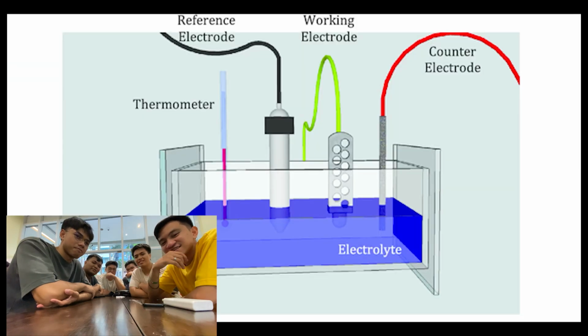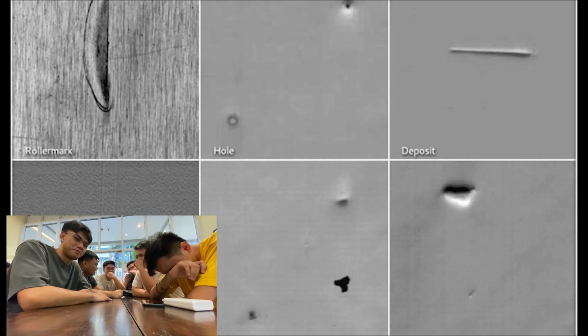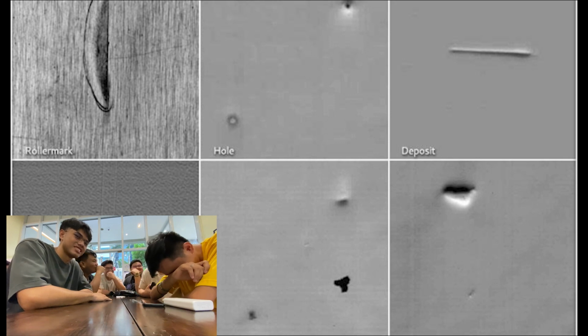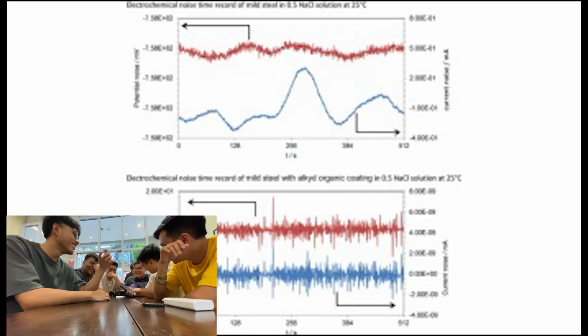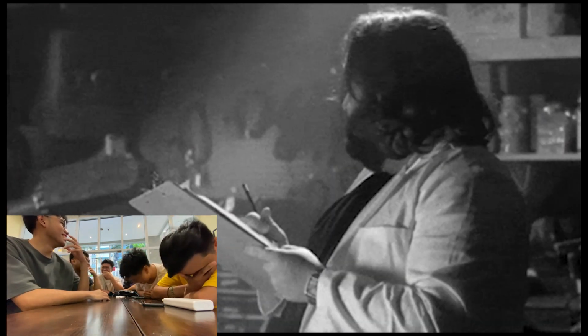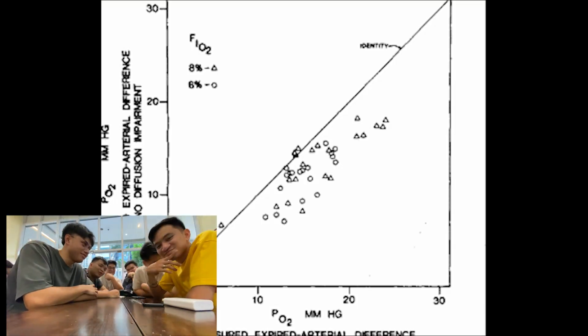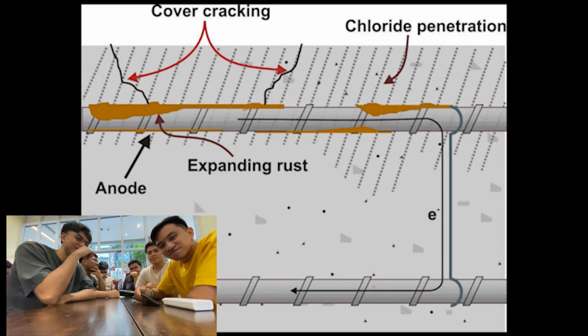Detection: detecting concentration cell corrosion involves a combination of visual inspection, electrochemical testing, and monitoring of environmental factors. For visual inspection, they look for areas of surface irregularities, including small pits or cracks, which may signify the presence of anodic and cathodic sites. Electrochemical testing techniques such as electrochemical noise analysis or polarization resistance measurements can provide quantitative data on corrosion rates and reveal the presence of concentration cells. And monitoring environmental factors such as oxygen concentration and temperature can aid in detecting conditions conducive to concentration cell corrosion.